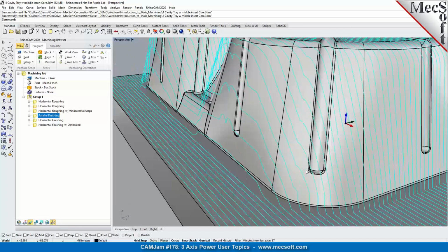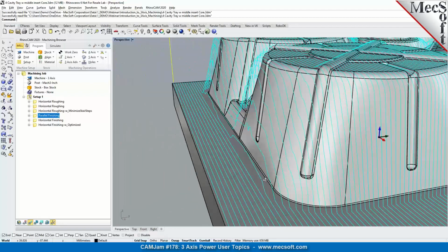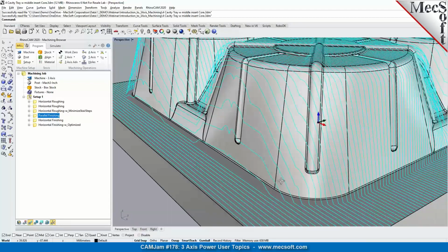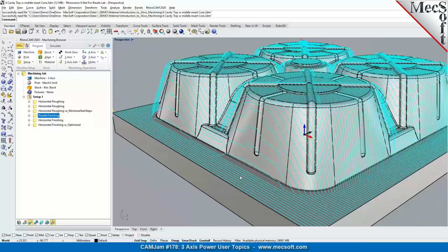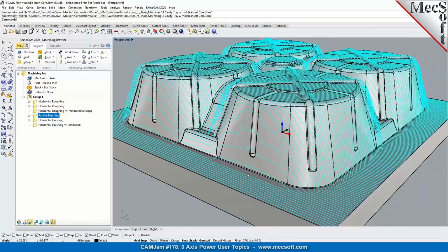If you have a very steep surface and the tool is actually riding on the side of that steep surface, even a very small change in the normal direction of the tool can cause a significant change in the vertical axis of the tool direction. So that's what you're seeing. You've got to be aware of that if you're cutting steep areas like this, and if you're going to go along that steep area like this toolpath is being illustrated here, you might see these jerky motions.